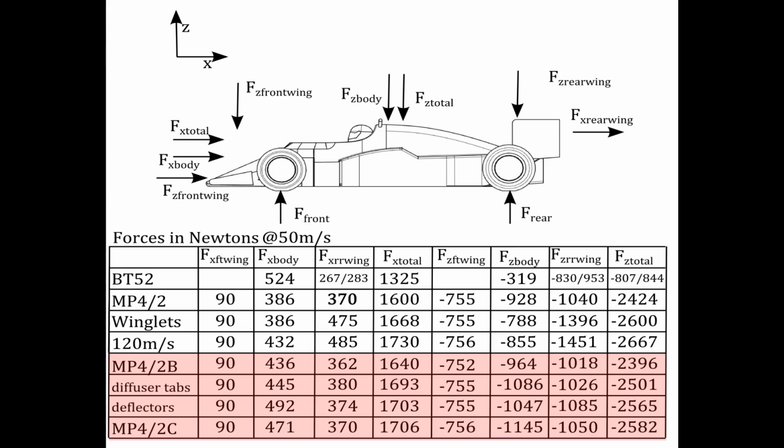This is something I really like about aerodynamics, its complete disregard for aesthetics. The previous windshield would seem to push the airflow over the cockpit, which it does, and should thereby reduce the downwind disturbance. But it doesn't, and the rear wing's lift-to-drag efficiency increases from 2.7 to 2.84.